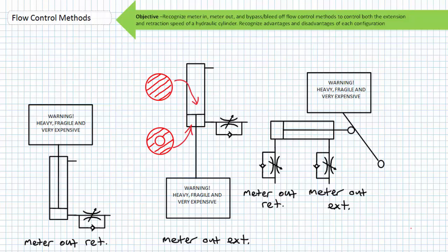Despite the fact that your pressure relief valve may be limited to, let's say, 700 psi, when this same input force and the lifted object are acting on the smaller area, obviously pressure in the rod end leg will be higher than 700 psi. One must take pressure intensification into account when specifying components and connectors for a system.